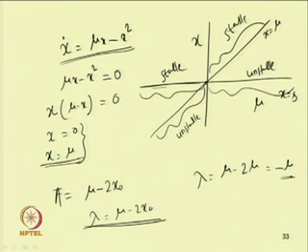So, after this point, which is a critical point, the number of solutions is not changing, but the type of solutions is changing. Here a stable branch becomes an unstable branch, and this unstable branch becomes stable. So, this point is a bifurcation point, and this type of bifurcation is known as a transcritical bifurcation. So, in the next class we will study in more detail the bifurcation of the fixed point response, and we will solve some more examples on this.